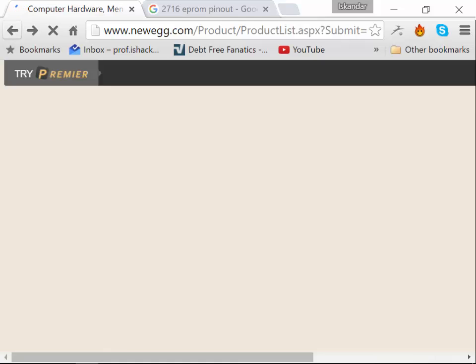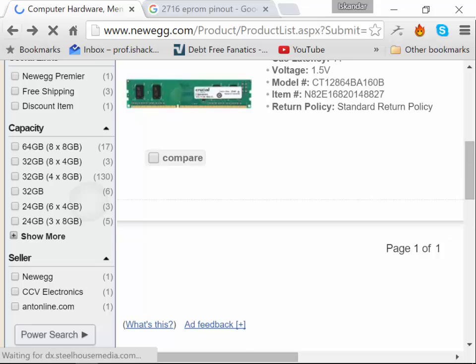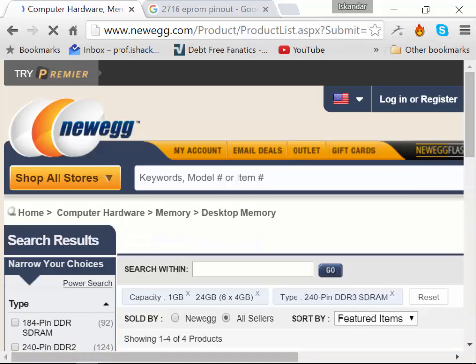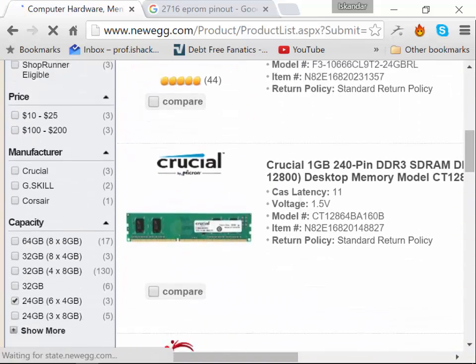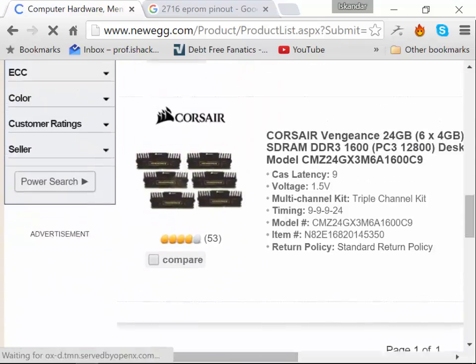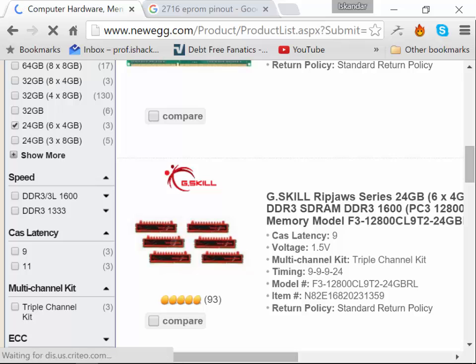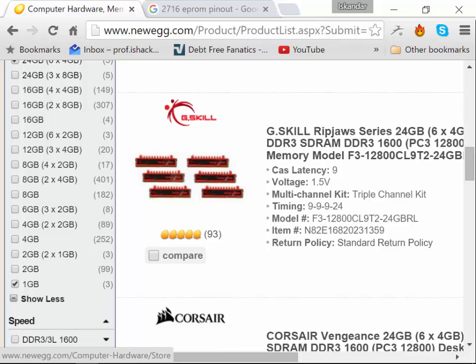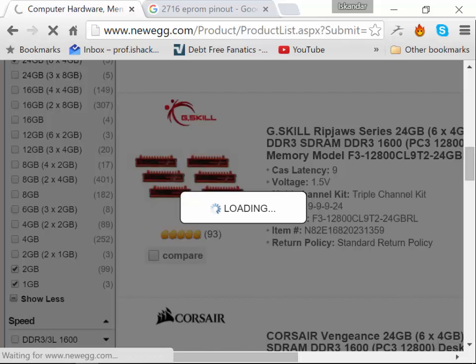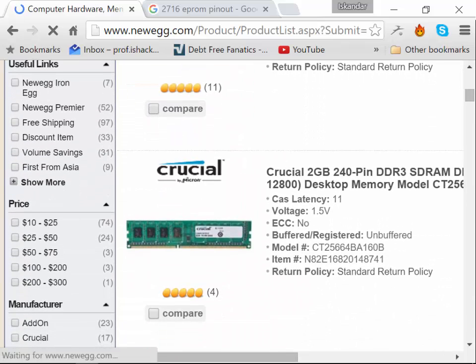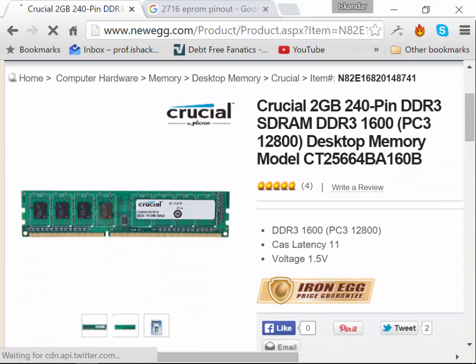When we look at DRAM, it's going to be some value like 1 gig by 1 or 1 gig by 2. SRAM and all ROMs are going to be something like 16 gig by 8, for example. So they're almost always going to be 8 bits wide, where the DRAMs are going to be 1 bit wide. This one has 8 chips on it.